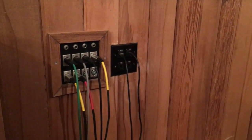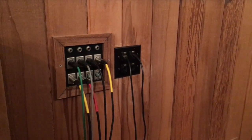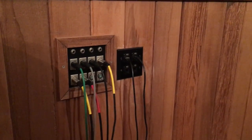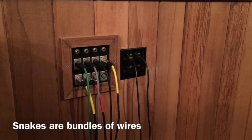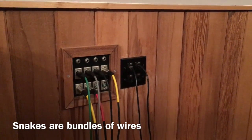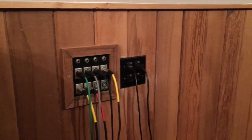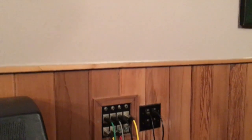And those are distributed from the control room, and those are sent out here using Cat5. So there's 2 big multi-channel audio snakes, they're called. One of them carries the analog signals from the mic inputs, and the other one is a Cat5 bundle which sends digital signals back, and those go out to my headphone mixers. Those snakes go up behind the wall, up into the ceiling, across the ceiling, and then they drop down kind of over here in the corner, and they come out.